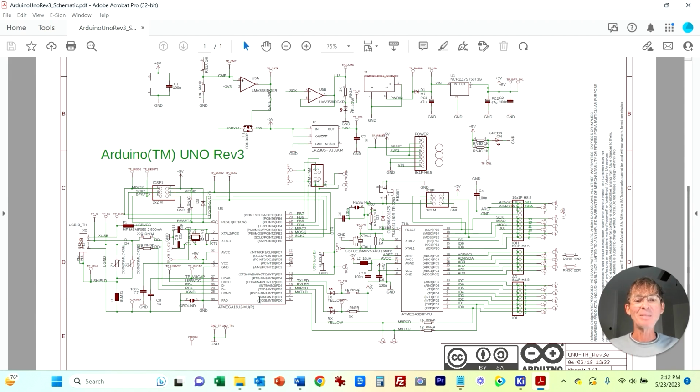So they've been around for quite a while, and they're expensive. Now, you can get much higher performance microcontrollers with much better resources, more memory, even more I/O, much higher clock speeds, native USB, and you can get them cheaper than ATmega. So just something to keep in mind when you are designing your commercial product.